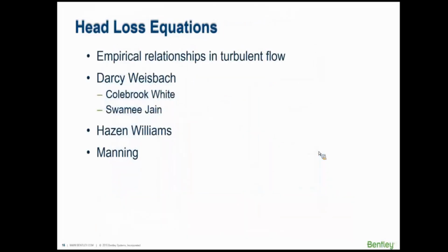The hard part is, how do you calculate it? Because in laminar flow, it's pretty easy. You can actually go back to F equals ma and the first principles of flow, and you can understand and calculate what the head loss should be. In turbulent flow, though, there's no single theoretically correct equation you can go back to and say, this is derived from the fundamental laws of nature. There are some empirical coefficients in any head loss equation for turbulent flow.